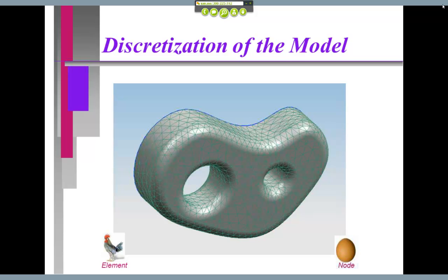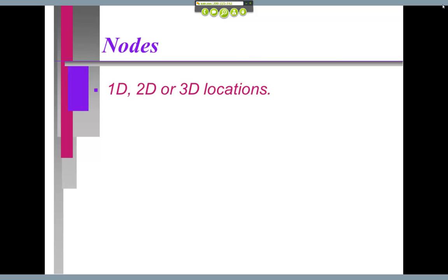We'll see that in just a second as we define what nodes and elements are. But it's always this question of, should I first blast out a bunch of points called nodes, or should I blast out a bunch of elements and then populate the elements with nodes? And it really doesn't matter. You need both. The reason that you need both is because the node is where all of the results are calculated.